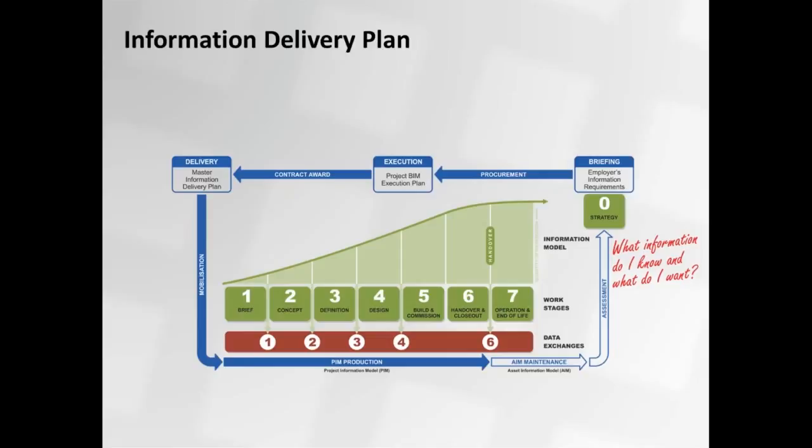I hope to be able to go very quickly through this idea once again so that it's finally cemented for everybody. This all starts from the information that the employer wants, given previous experiences of how they want to improve on the process. And then the BIM execution plan is the response of a design team to this. It is supported by an MIDP, a Master Information Delivery Plan, which is the sum of all those documents that we've seen that detail who's doing what and when.